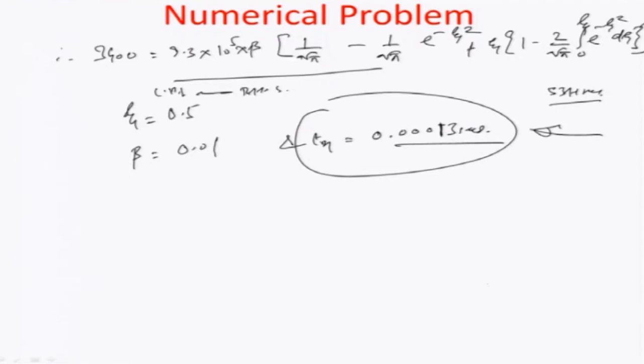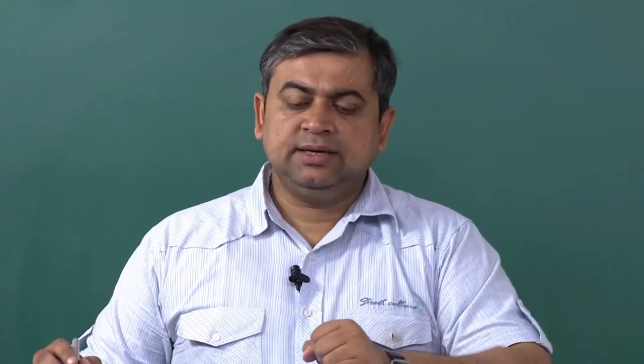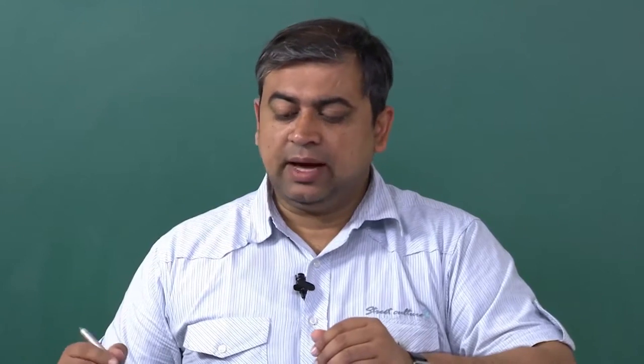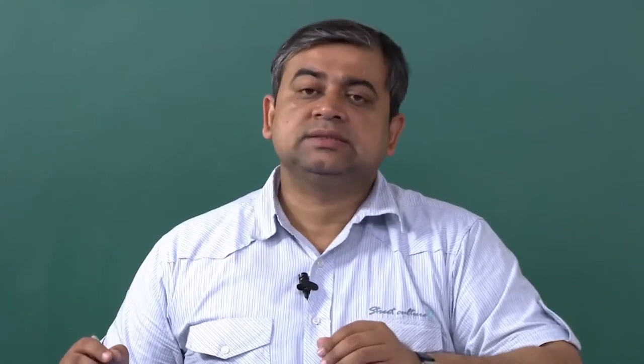So the time of machining in this particular case, as you can see, 0.00013 is very large in comparison to the time of machining which was earlier for a semi infinite region, for obvious reasons that you are trying to reduce the beam area from a semi infinite interaction with the workpiece to almost a small value of the diameter d equal to 200 microns. Okay. So therefore more time would be needed for this machining to happen because of heat losses across the beam boundary to the remaining part of the solid.